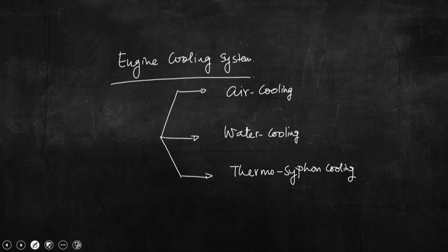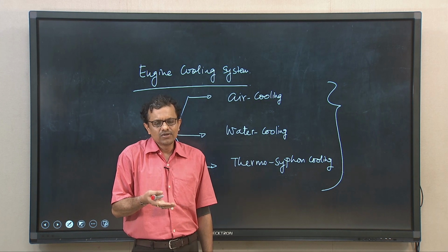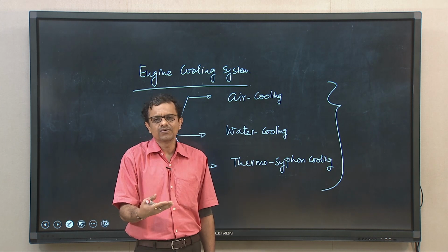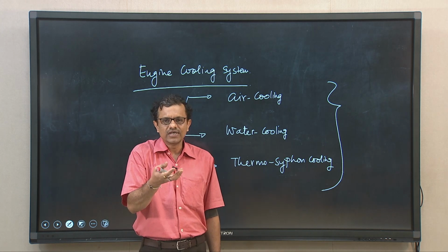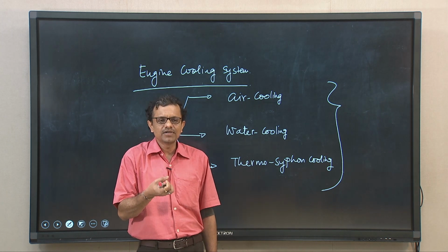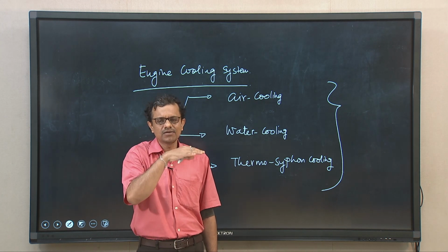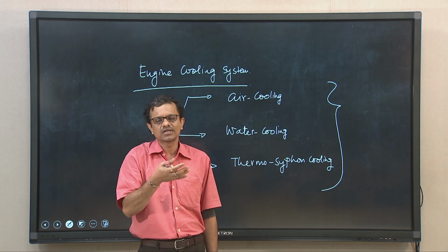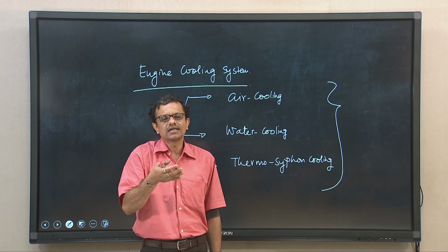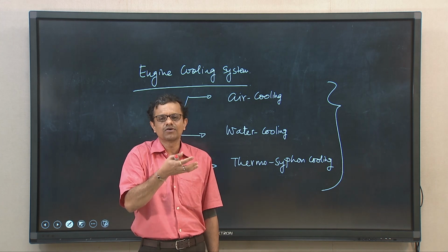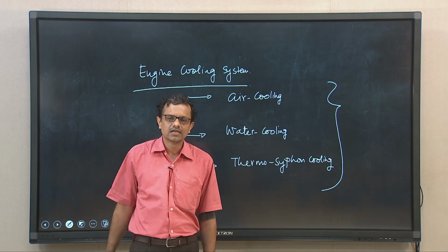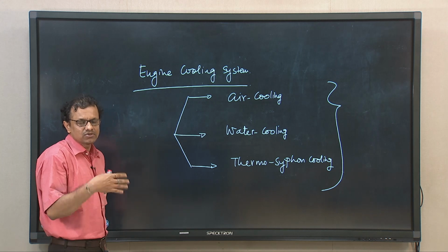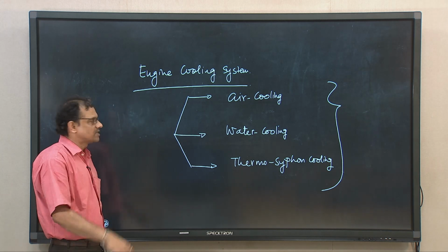Okay. So, now let us discuss what an air cooled engine is. Air is available in plenty. When any 4-wheeler or 2-wheeler moves, the forward movement allows the engine to intake a certain amount of air, and if that air can be drawn properly into the engine system, the incoming air can be used as a coolant. After taking some heat from the engine, that air is exhausted into the ambience again. Certainly, you are going to have some air pollution, but this is the concept of air cooling.